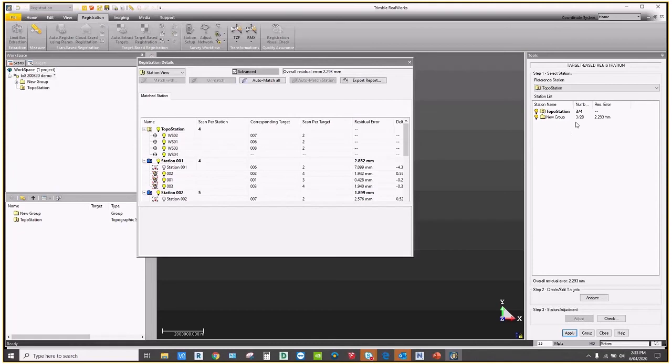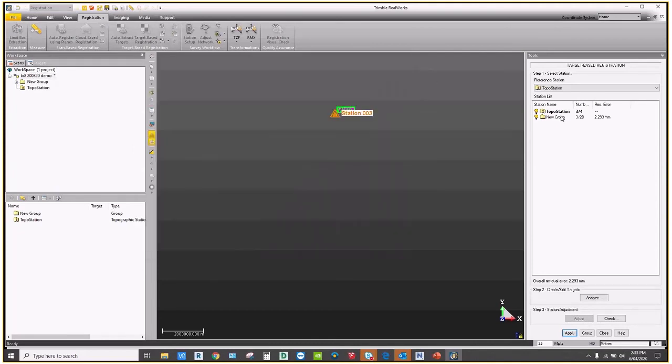But this time, what it's telling me here is that out of the 4 points we had in our control file, it got a result to targets or stations for 3 of them in our point cloud, and it's telling me there that it had 20 stations and targets all up, but it used 3 of them to georeference the data.